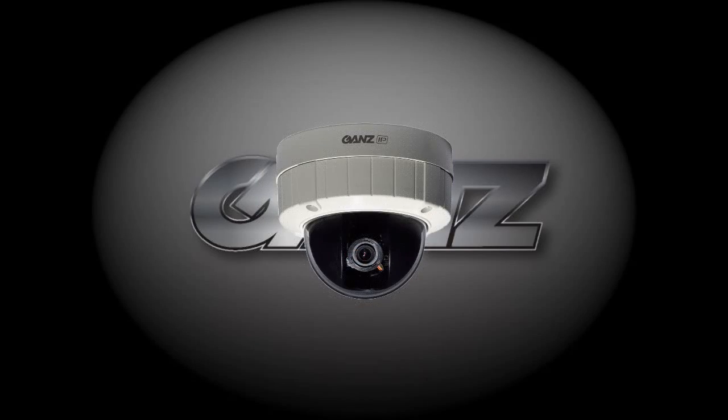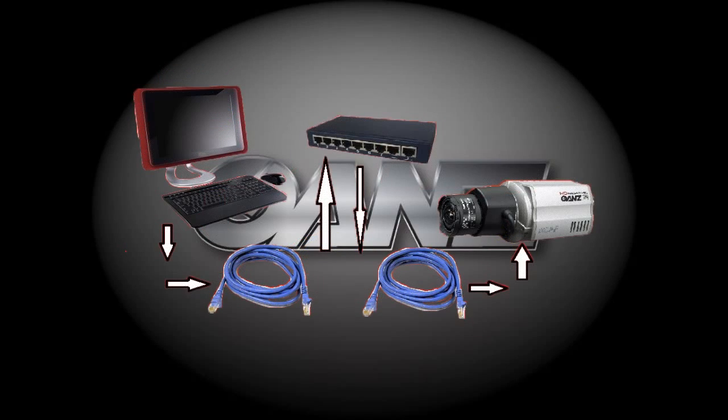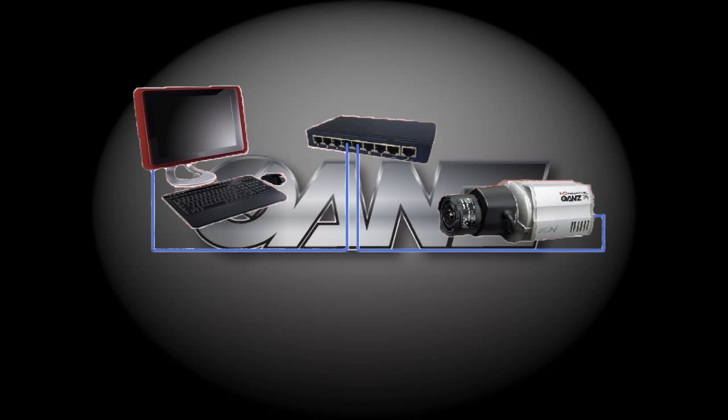There are two different ways to physically connect to the Pixel Pro camera. One is to connect a PC or laptop directly to the Pixel Pro camera by way of a crossover cable and provide power to the camera by way of an AC or DC power supply. The second way is to connect a PC or laptop to a PoE switch by way of a Cat5 cable and then connect the Pixel Pro camera to the same PoE switch.